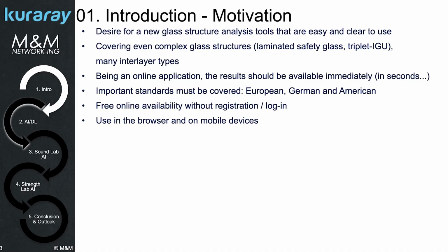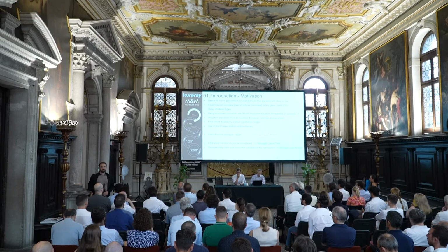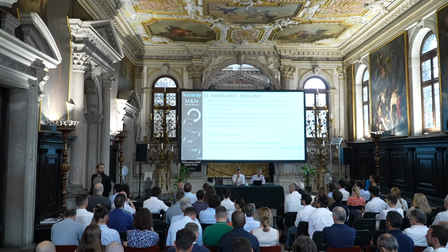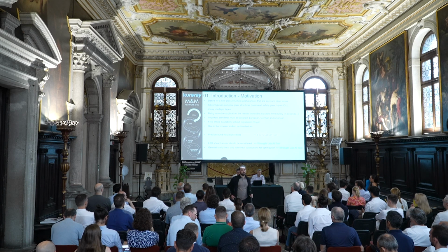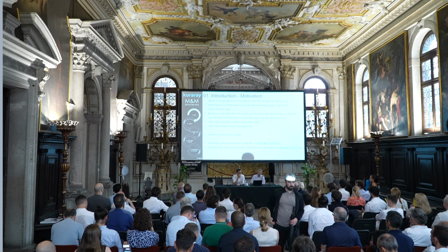And when it comes to more complex calculations, or let's say if it's a facade supported window and not just a beam situation, you can also choose between a linear and non-linear calculation approach, which is quite important for optimization of the glazing construction, so that you can really downgrade the glazing thickness to the minimum.